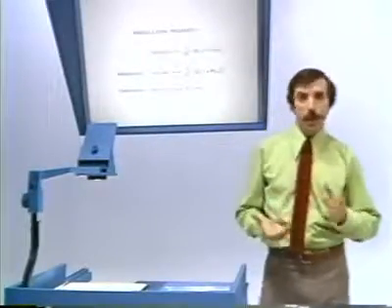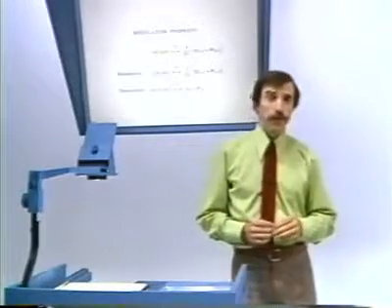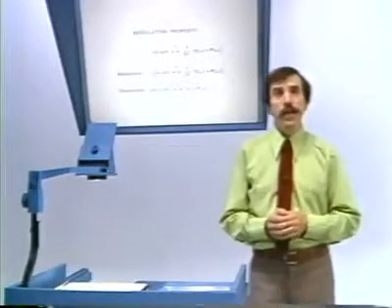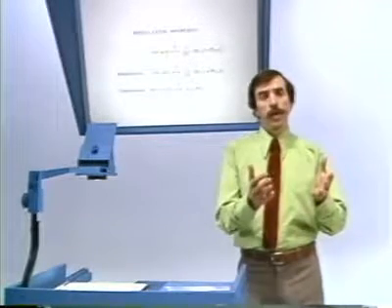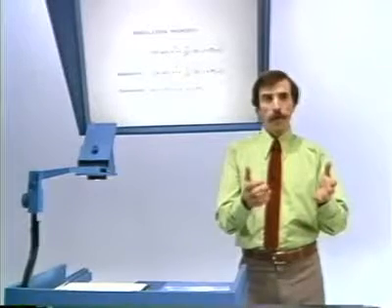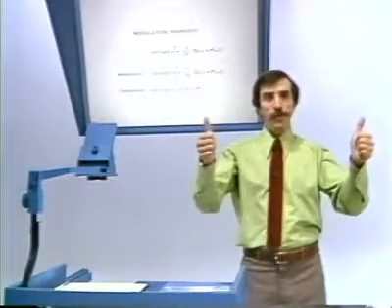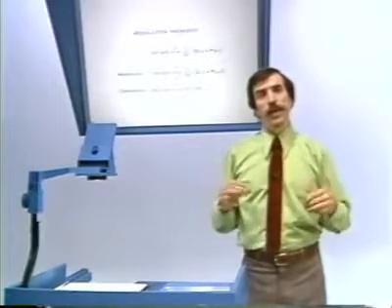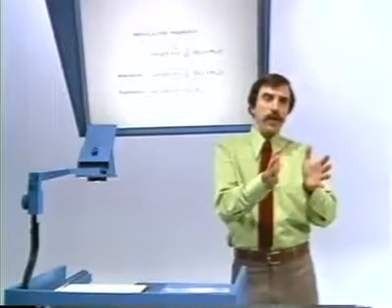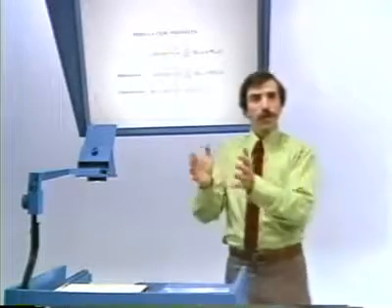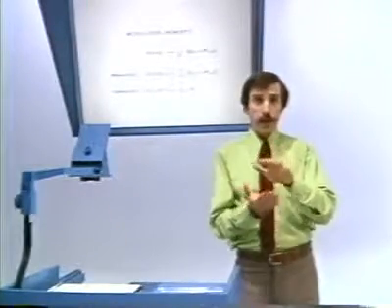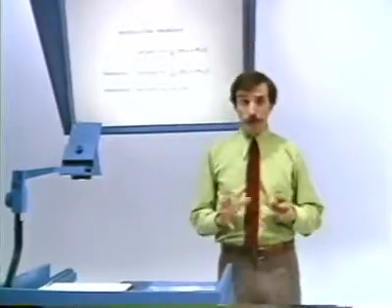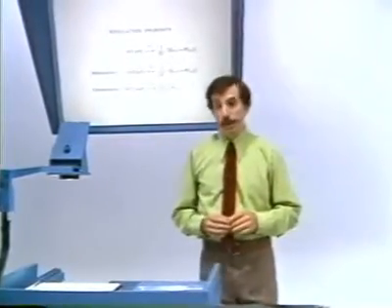And what the modulation property, as we'll see when we explore it in more detail, tells us is that if we have a signal with a certain spectrum and we multiply by a sinusoidal signal whose Fourier transform is a set of impulses, then in the frequency domain we convolve, and that corresponds to taking the original spectrum and shifting it in frequency up to the frequency of the carrier, namely the sinusoidal signal. And as I said, we'll come to that in much more detail in a number of lectures.